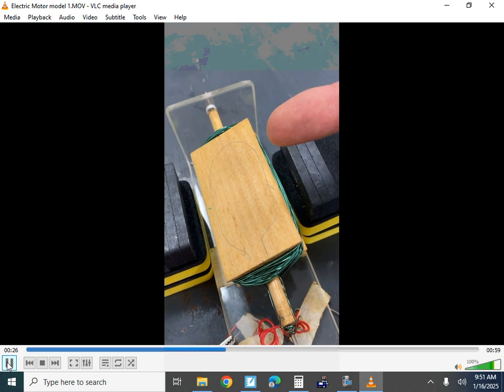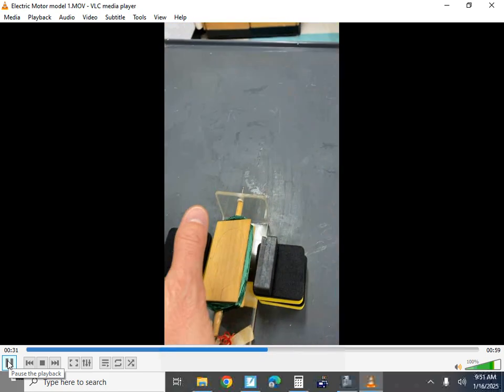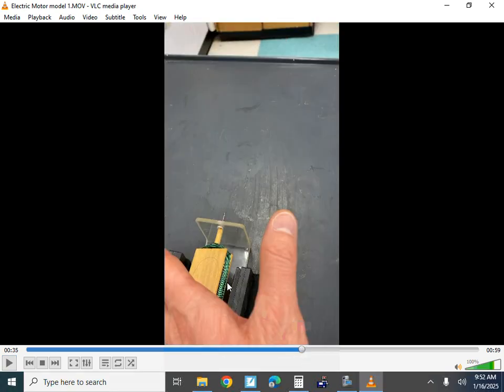Anyways, let's show you north going that way. I've got electrons going this way, and so on this side of the coil, I've got a push down. So just catch that there: on this side, this is the electron flow direction, this is the north, and so the fingers are stretched out this way, away from north, and my palm is facing down, so there's a force down on all of the electrons running through all of these loops of wire on this side. Reverse the logic, and you're going to have a push the other way on the other side, right? So down on this side, up on the other side, and so this motor is going to turn this way when I turn the electricity on.